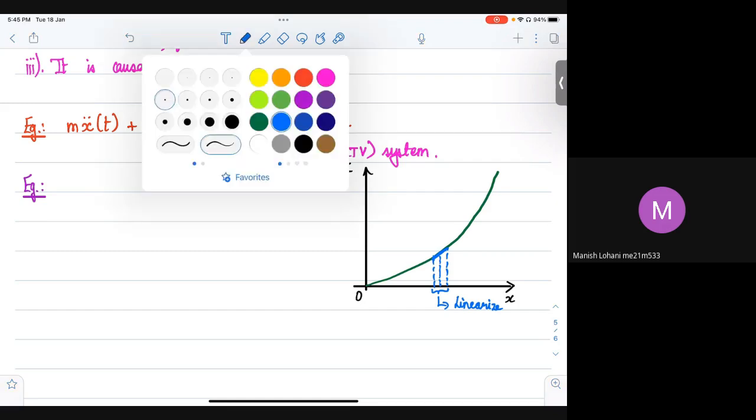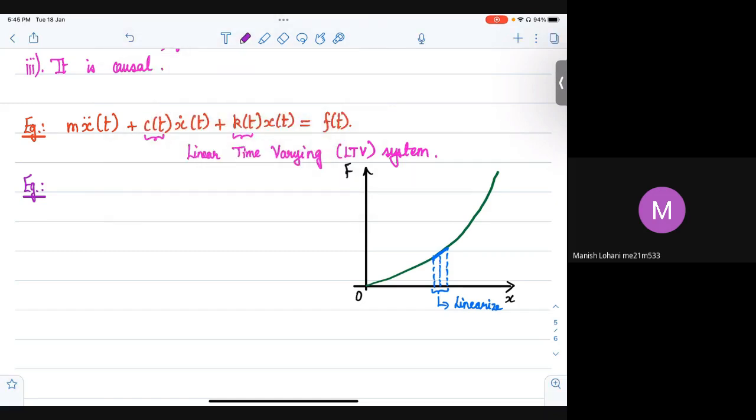However, consider a case where my spring is going to be compressed and expanded in this range of displacement. That may happen in some applications. But if you look at this in a bigger range of operation, we can immediately see that I can no longer fit a linear curve, because I will get a huge error if I try to fit a linear curve there. So then I need to write a non-linear model for the spring and work with it.